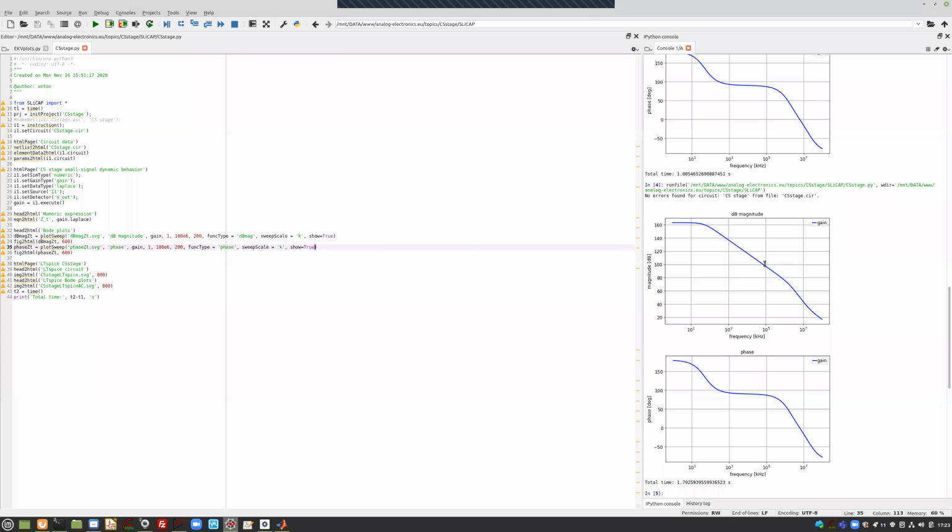And here you find the same characteristics as we did with LTSpice, but now with the EKV model. 2 poles and a 0, and the phase going from 180 degrees to minus 90, which is 270 span. The position of the 0 and the second pole are a little bit different, because the output capacitances have not been modeled very accurately. So that is why you find a little difference between the two models.